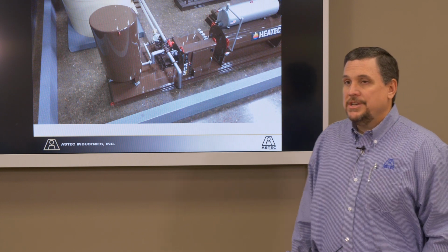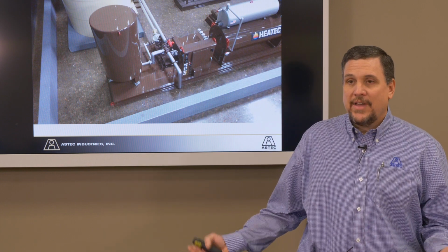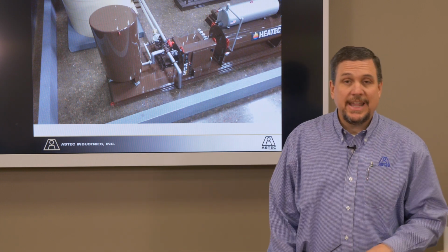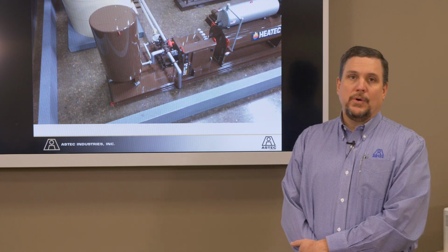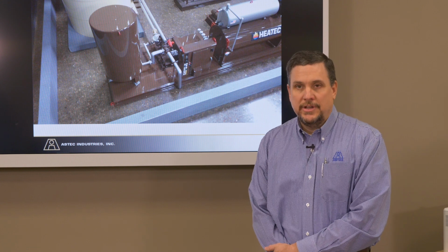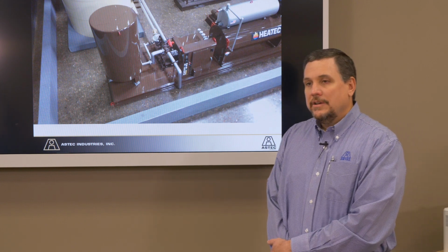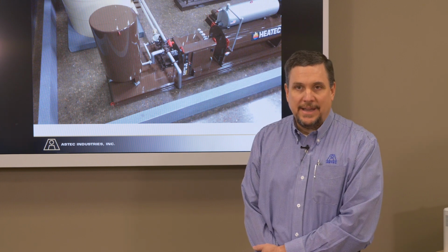Most of these calibration tanks, all manufacturers build them. All of them hold right around 1,000 gallons. That 1,000 gallons is somewhere between 4.3 and 4.4 tons of AC. Use them as you should. Put 3,000 or 4,000 pounds in them. Don't underutilize them and put 400 or 500 pounds in them.